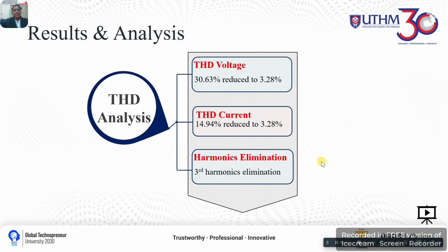Next, the THD analysis for voltage and current showed that both harmonics have been significantly decreased after implementing the filtering component. The decrease in harmonics was mainly contributed by the third harmonic elimination.